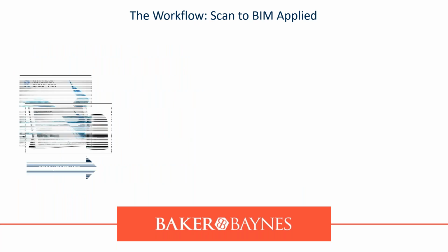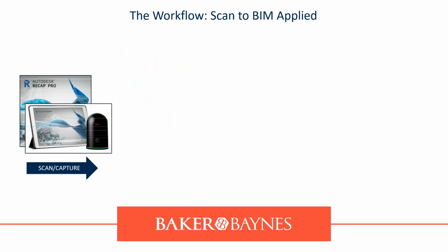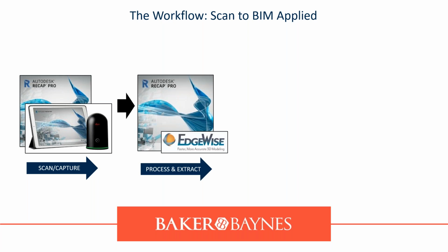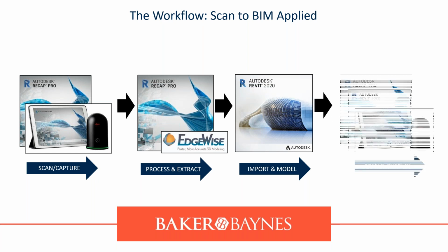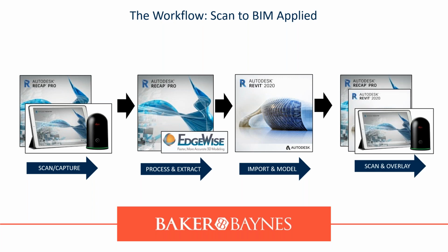And of course, I like pictures because I'm a designer. So this is what we've done. We first did the scan and capture part of things, where we used Recap Pro with the BLK 360 to capture the environment. Thereafter, we processed it on the desktop with EdgeWise and Recap Pro. We then jumped into importing that extracted model into Revit and modeling from there to the layout that we desired. And then the last part of any workflow is the as-built compare versus design intent.